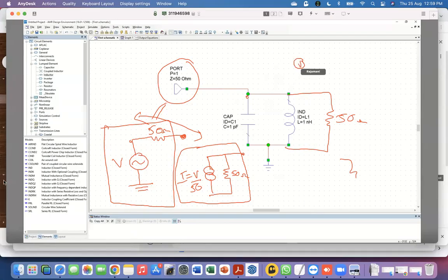If you had a low frequency situation where you had a voltmeter, a voltage source, and you were driving some resistance R, right? If you want this voltage to appear entirely across this resistor, which is your goal, then you would not like any other resistances to be present here. Now, this resistance could be the source resistance of this circuit. If that happens, you will not get the entire voltage dropping here. You will not get the entire power dropping here. And that's what you would like in the ideal low frequency case. In reality, you would like the same thing to happen even at high frequencies. But as I said, it's not possible.